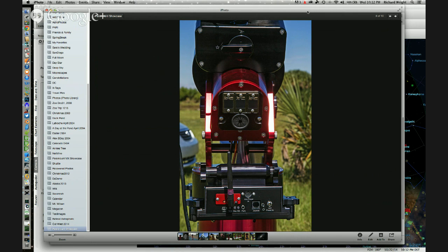Sometimes they'll have one USB controller, and even though you've got 3 or 4 USB ports on your laptop, it's actually doing a time slice, and it's sharing all of those USB ports on really what's one USB port. The more expensive laptops will have a dedicated controller for each USB port, and those are a lot more reliable, certainly for remote applications. But even if you're not remote and you're setting up, you really don't want the hassle of USB things crashing on you on a regular basis. But our hub is industrial grade, and it meets the USB specs. And when it gets cold, it doesn't quit working, or when it gets a lot of dew, it doesn't quit.